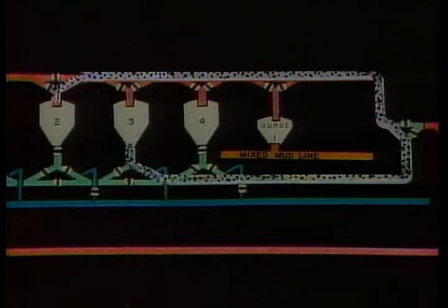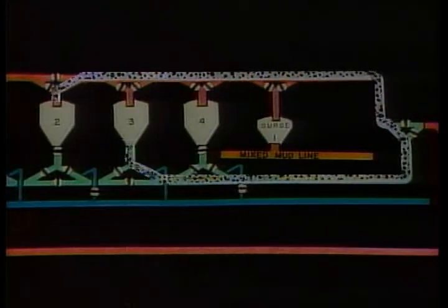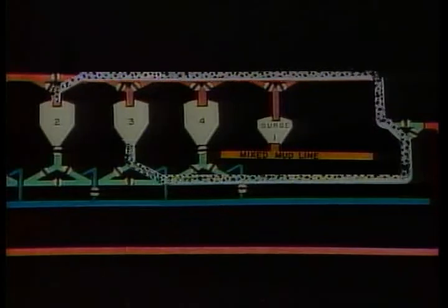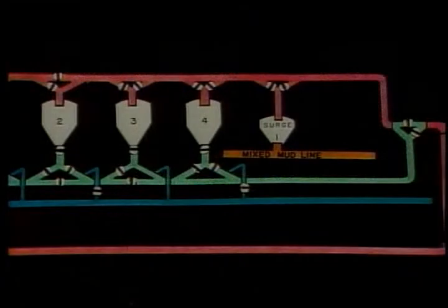Then, when you open the discharge valve, bulk will flow from the source tank, through the fill manifold, and into the destination tank. At the destination tank, the air vents overboard, leaving behind the bulk materials. Once the material has been transferred, the source valve is closed, but the purge valve is left open for about 10 minutes to blow the residual bulk out of the lines so that it doesn't settle in the lines and clog up.